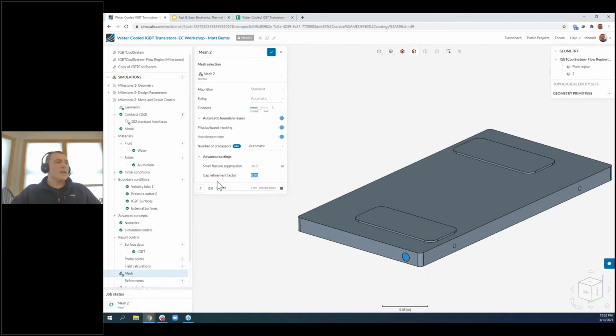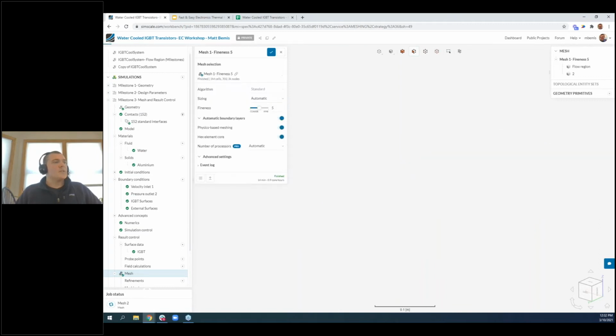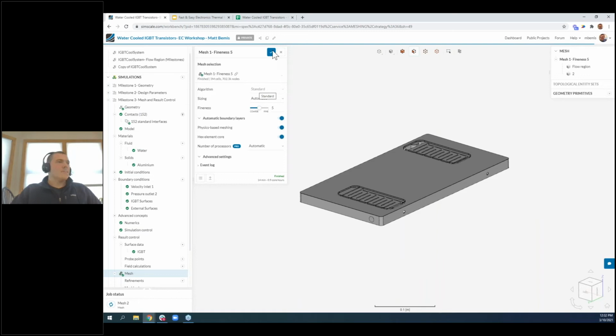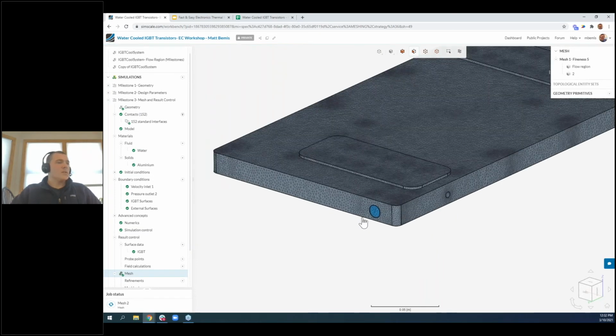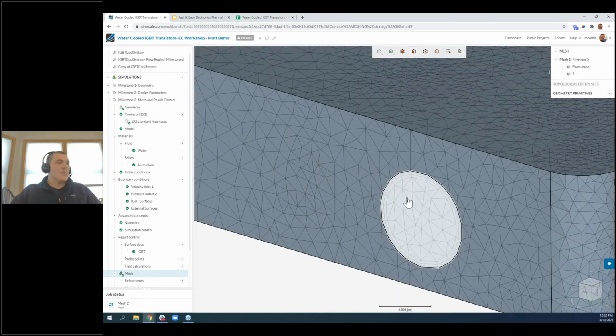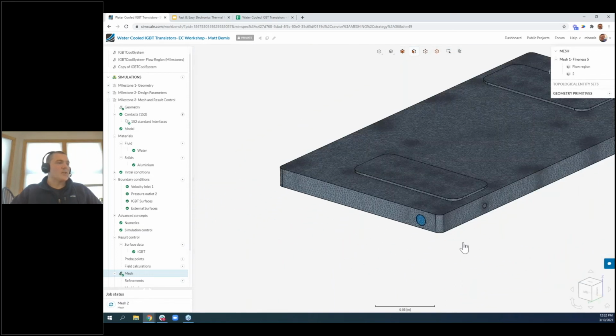And instead of waiting, say maybe 10 minutes or so, let's go back to that mesh 1 fineness. We see it was 3 million cells. It took 14 minutes to generate. And a few things to point out here, right? So we do see those wall layers, and the number of cells through the channel here looks great. Overall, this is quite a bit of density. I'm happy with this, and we don't need to change it.